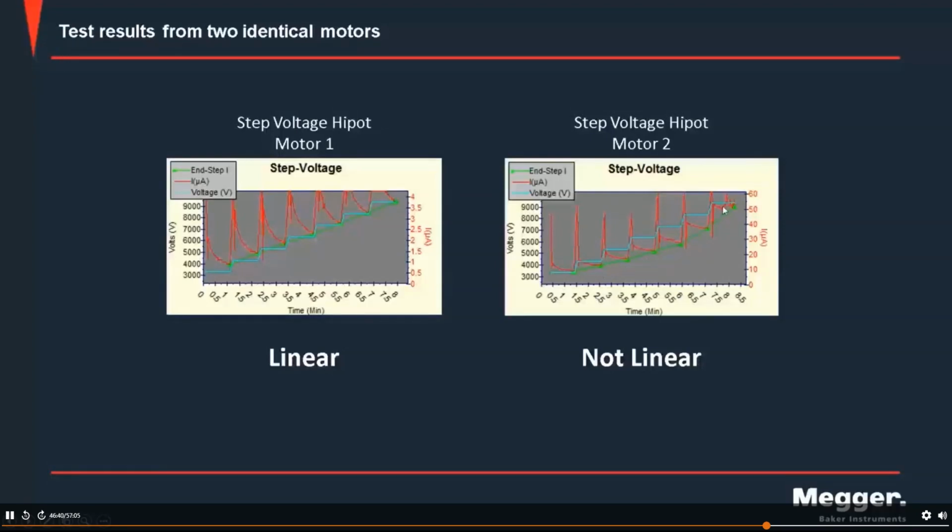It starts out linear, and as we approach the higher test voltage, the recommended test voltage, in this case from IEEE 95, we see this nonlinear response. And then we also see the characteristic of the current, where it's nice and smooth asymptotic decay. On the last step, we start to see an erratic nature in that current. And so this test in the AWA data is listed as a pass, but we have some qualitative and quantitative, actually, indications that there's instability in that insulation.